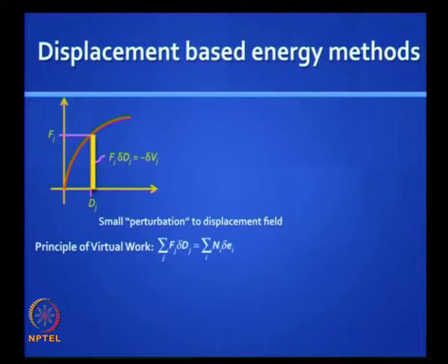So, let us take for example a truss, and to generalize, let us assume that all the elements are elastic but not necessarily linearly elastic. So, if the elements exhibit non-linear elastic material behavior, then the loads, the deflections that happen at the joint locations, the so called external component of the force field and displacement field, will also show a corresponding non-linear behavior.